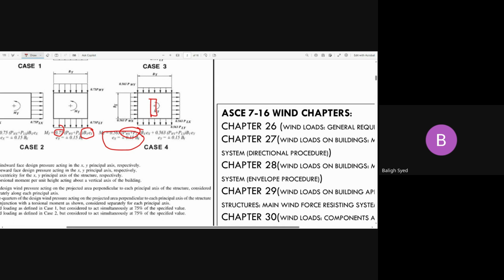They must apply all these provisions during the wind analysis of the structure. Okay, they must apply them. There is no way the wind is not going to produce torsion on those structures. It's impossible. After a tornado or after destruction, we have seen the problems over there. Those kinds of structures, which are 100% rigid, 6 or 7 story structures, must apply these provisions. Okay.